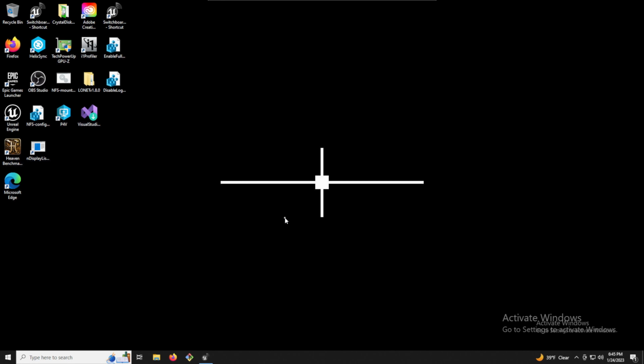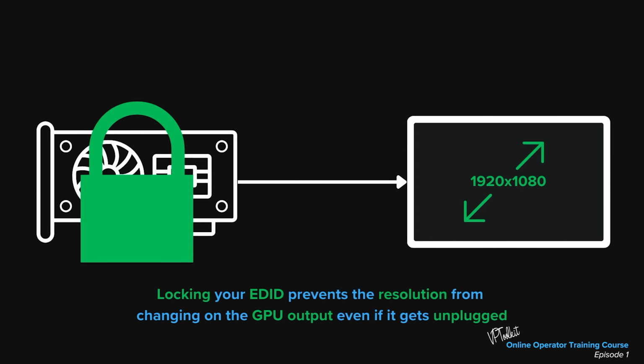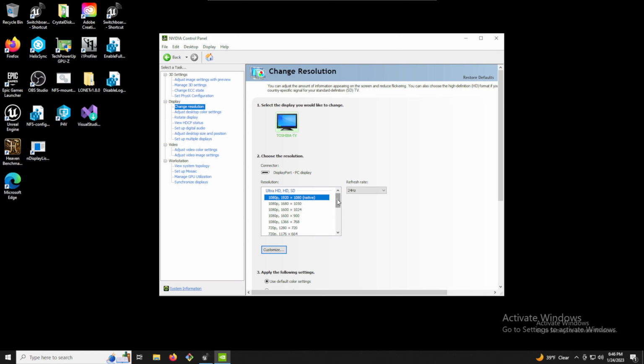I'm going to show you how to change the EDIDs. So what we want to do is make sure that we basically lock the output of the GPU. So once you've saved these settings and then loaded them again, you'll be able to lock the GPU's output. So if it comes undone or anything like that, you don't have anything fighting your signals. This helps for when you have multiple render nodes in a cluster and you want the Genlock to be supplied by one machine. You can set them up like this and they should not change while you're doing configuration or testing or changing other things.